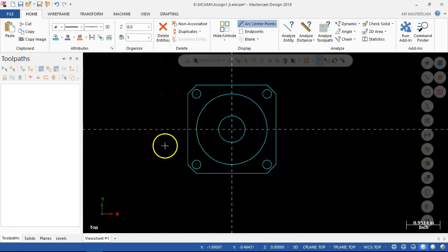So we talked a little bit about selection for stock. One of the things I'm going to do at the end, I'll warn you up front that I jump around. That's the way I program. There's nothing linear. If I think of something, I address it. All right, so we're going to face, we're going to contour the perimeter, we're going to pocket through the center, we're going to decide if we're going to load up drill bits, or if we're just going to take the 1/2-inch end mill and plunge it through. All right, maybe it takes 2 or 3 minutes on some operations. In that case, I can justify loading up a second tool, 3/4 inch tool, and probably a pilot drill.